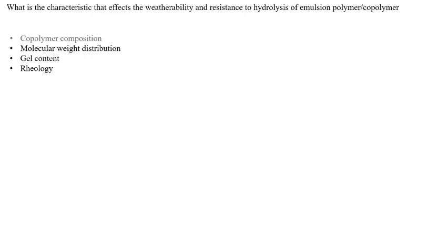In that case, copolymer composition will affect the resistance to hydrolysis and directly affects the glass transition temperature. The glass transition temperature will be shifted because of the hydrolysis phenomenon. Why? Because of the presence of water between the polymer molecules, in the free volume space, the humidity will accumulate in such a way that the copolymer composition itself governs how the glass transition temperature is affected.